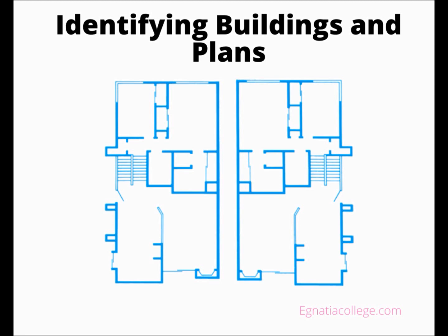One technique that is used to create similar, yet different, plans is to reverse them. A reversed plan is created by building the plan as though seen in a mirror. The reversed plan has the same features and the same dimensions, but their arrangement is reversed. In Building 2 of this development, the south end is a reversal of Plan A. This is designated on the site plan and in this figure as AR. The letter R indicates a reverse plan.